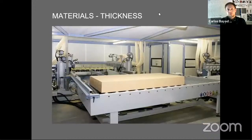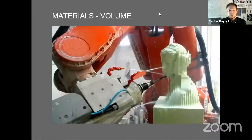When working with a 3-axis milling machine, it's all about carving the material from the top. So there is usually a maximum thickness that you can actually use for generating your relief. Whereas when you are operating with a multiple axis milling machine, it's all about the block of material that you will be cutting from the different directions.